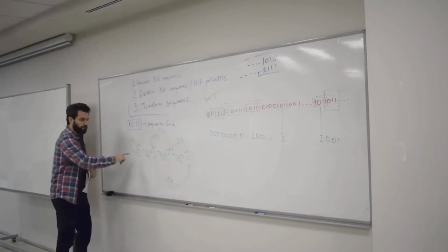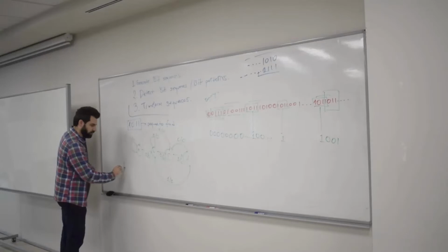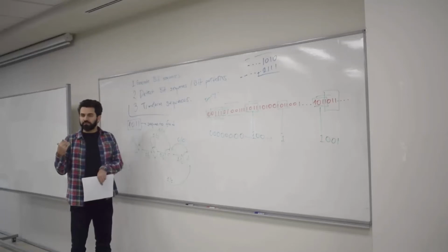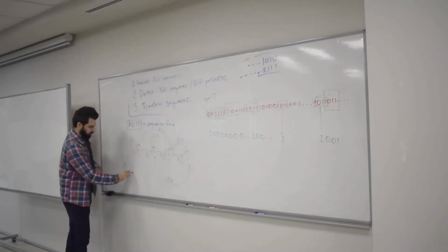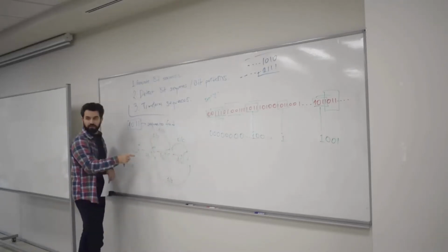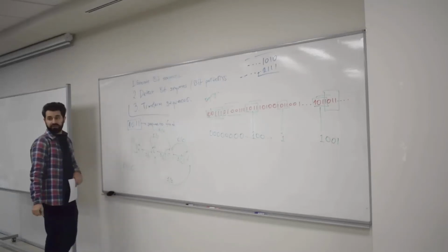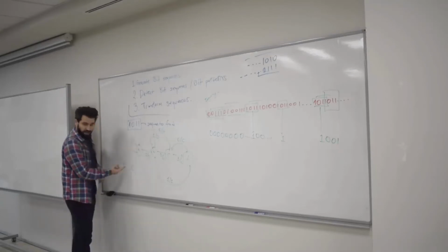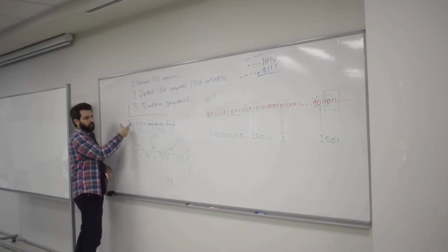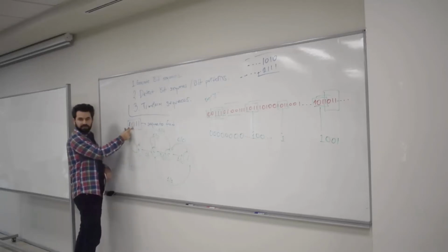So let's come back to your question. When I'm in D, that means I've already seen 1, 0, 1. Now I'm thinking about the next bit. If the next bit is 1, then I complete this cycle, so the pattern is complete. That's why I go back to B. But if I see 0, that means I have gotten the input sequence 1, 0, 1, 0. Now I'm thinking about the sequential pattern that I'm looking for. In this pattern, I see that the prefix, the beginning of the pattern, has a 1, 0.